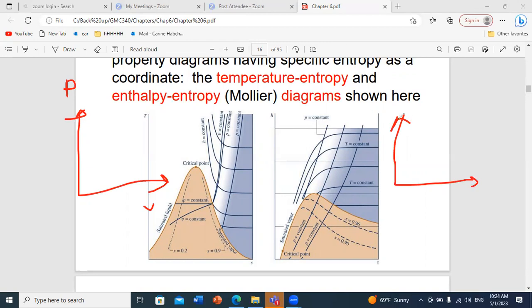And keep in mind that for a closed system, we know that the work is the integral of PdV. We'll see also when we continue that we can evaluate Q as the integral of TdS. We'll see how. This is why the graph of T as a function of S will be helpful for us in order to do the analysis of cycles.